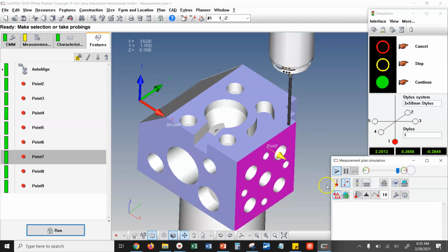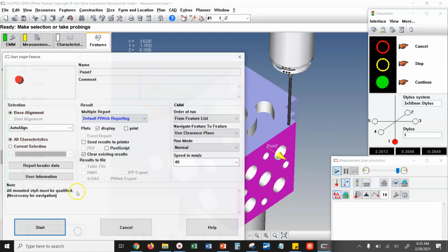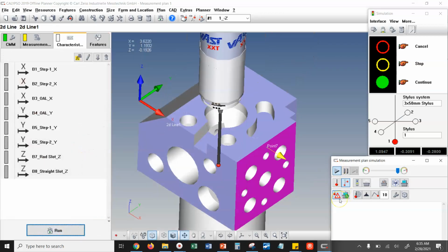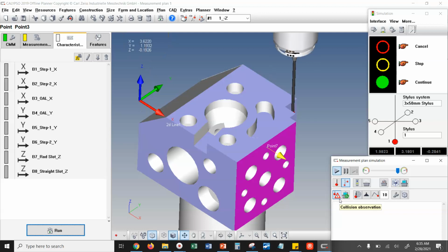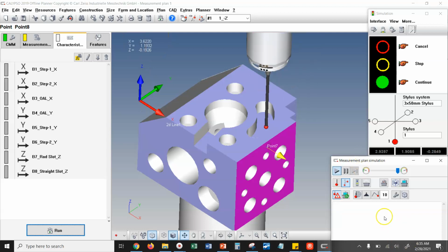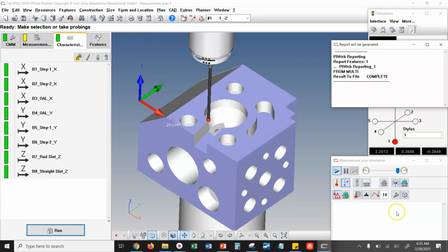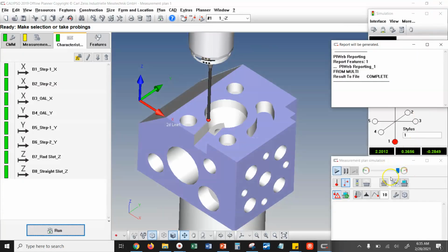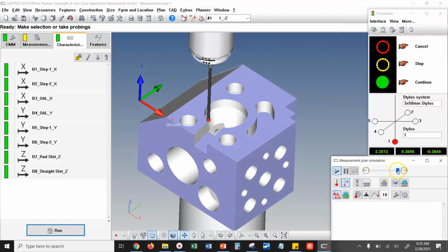It does not work if you're at full speed on that simulation. So we'll rerun the exact same simulation again. We're going to let it run at full speed, and sure, it'll run faster, but it didn't log any of those collisions. So how is that helpful? Not helpful at all. So again, I just can't emphasize enough that you want this speed slider here to be at 90%. So just click one arrow over, or mouse click a little bit to the left of full speed when you're running that. Otherwise, you're not doing collision detection at all.